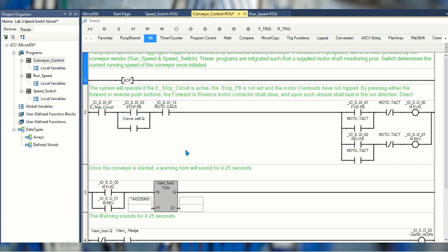Okay, so the first run looks like a normal stop-start. Now, it was not a part of the project, but I installed an e-stop circuit bit to allow for that, and it would be just like all the other devices that are normally closed and are being looked at to see if they're energized. We use the normally open contact.